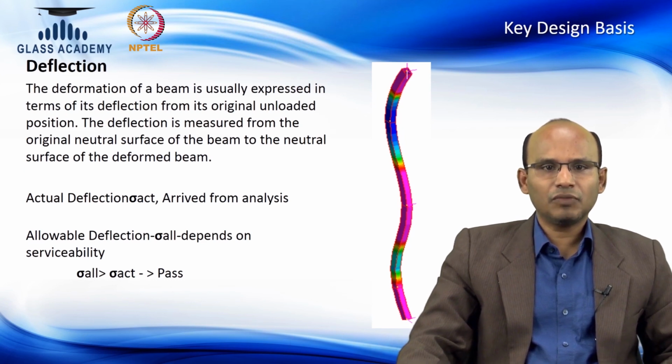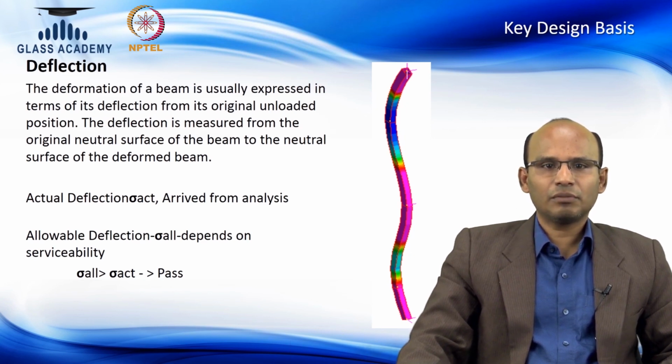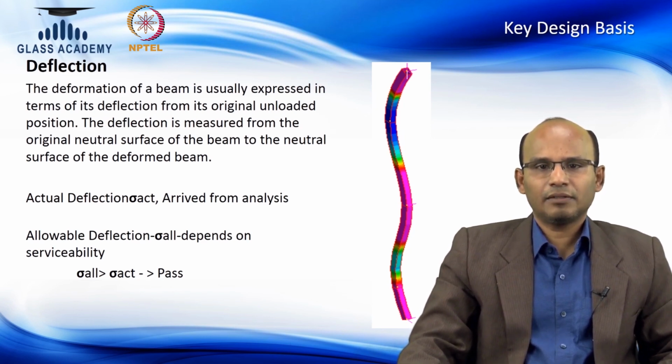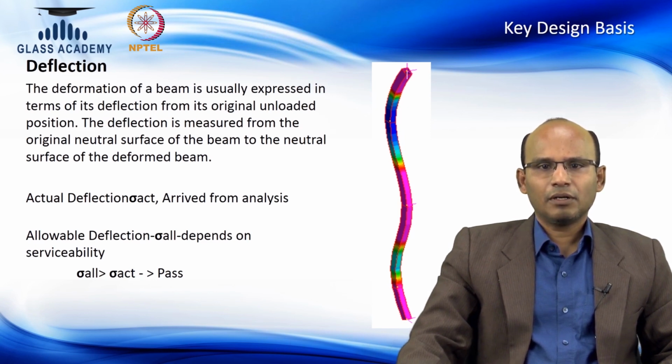Deflection check is needed for glass and glass-supporting framing elements. Deflection generally follows the beam deflection theory for framing elements, and for glass checking it follows the plate analysis theory. The beam deflection theory could be for a continuous beam or simply supported beam, or if it is more complex, it requires a computer analysis so that the behavior of the beam is predicted correctly.